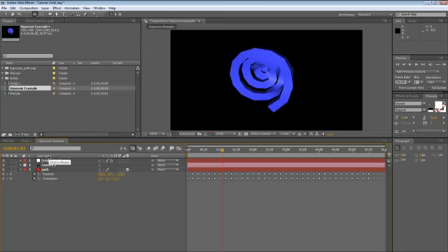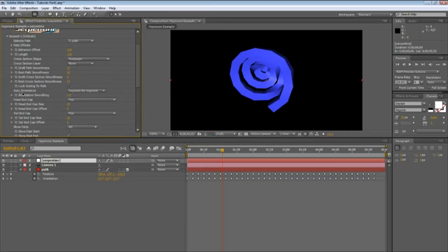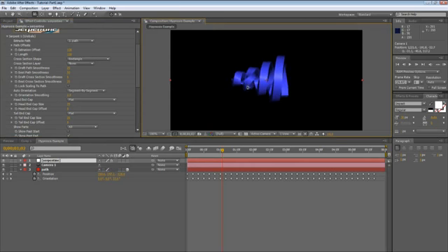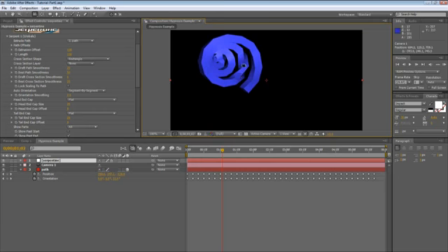Now, Serpentine offers you these auto orientation options. The first one, which is now the default, is segment by segment. And as we can see, it's not really working that well, because this twist here is not supposed to be here, and also there's another one right here that shouldn't be there.